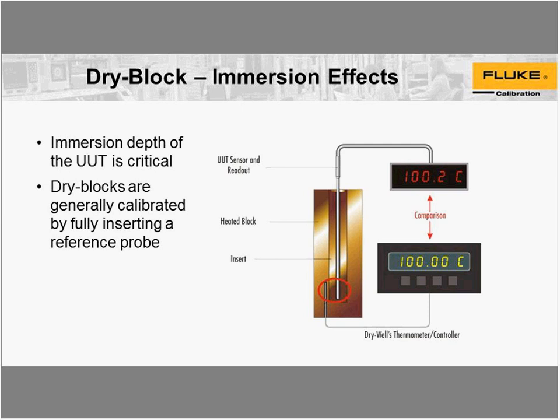The method that you're seeing here can be used, or this is typically how it's used to calibrate the well. If having a UUT, you're going to use a higher sensor and align those closely for the calibration of the well with a much higher accuracy reference probe. So again, it goes both ways with those. It just depends on where your reference lines up as far as uncertainty.